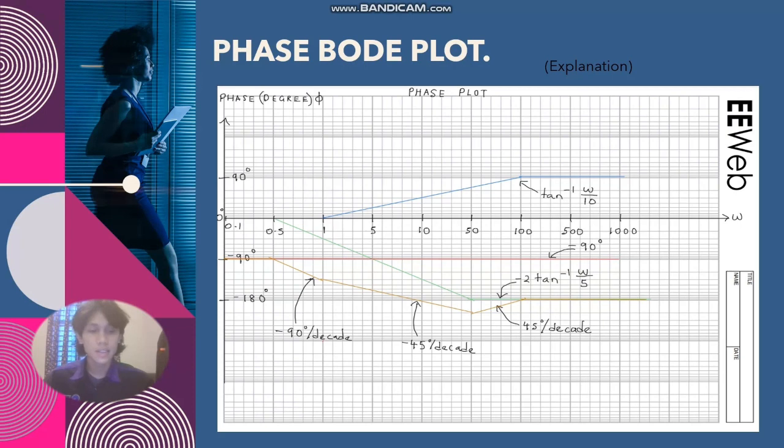The greater the margin, the better, because higher gain and phase margin means greater stability. That means a loop with a gain margin of 0 or even less will only be conditionally stable and could easily become unstable if gain changes.